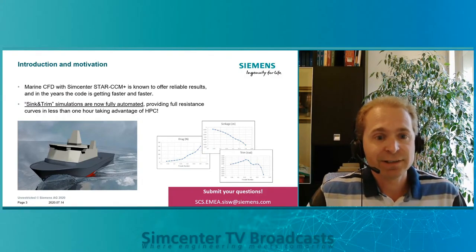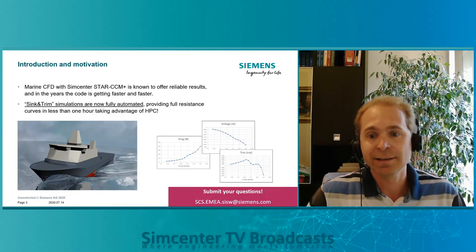However, let me highlight that even for this application, lots of effort has been put in place recently, with a special focus on automation and on performance. Now we can claim that starting from a new hull, we can provide a full resistance curve in less than an hour, taking full advantage of HPC.